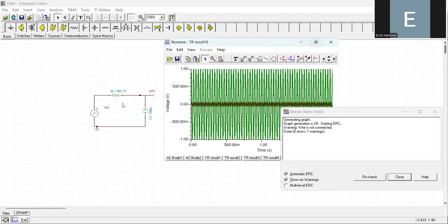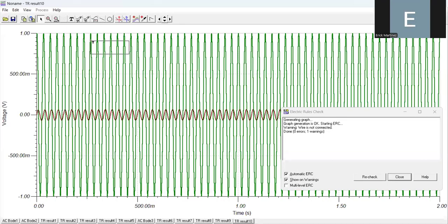And you can see that now the output voltage has a lower amplitude compared to the input voltage. And that is a consequence of the filter, no? Because I am introducing an input sinusoidal that has a frequency greater than 2 hertz. And for this part of the simulation, I use a value of 30 hertz.